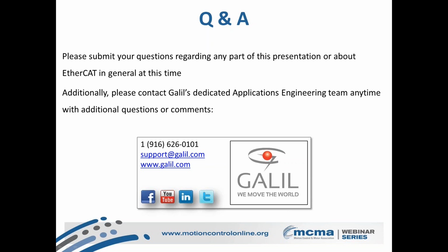Yeah, this is, like I mentioned, probably one of the most common questions we get from customers calling in about EtherCAT. And as always, the question is, what is the application exactly? If the application needs tightly coordinated motion or control over a large physical footprint, over a large distributed area, then EtherCAT may be appropriate. However, if you're building a 3-axis CNC machine, it's all going to be enclosed in the same box. There's really no advantage to using EtherCAT in a system like that. And so in that case, we would advise staying with the standard analog control and encoder feedback system as opposed to EtherCAT.